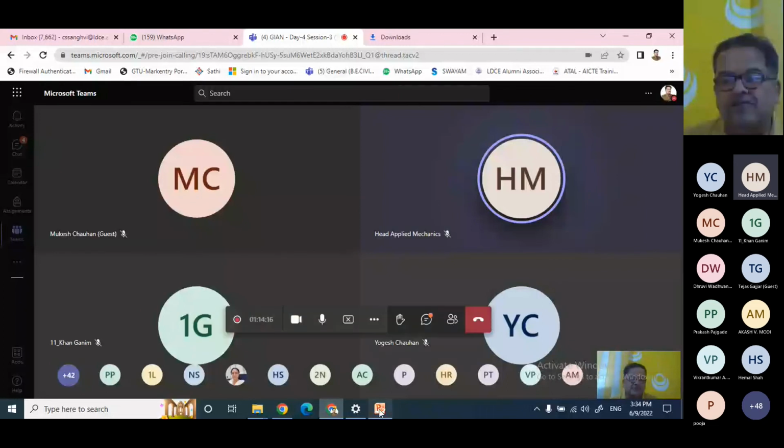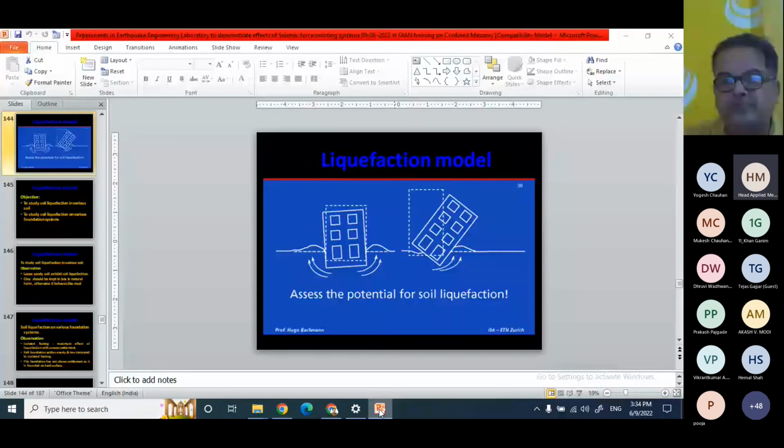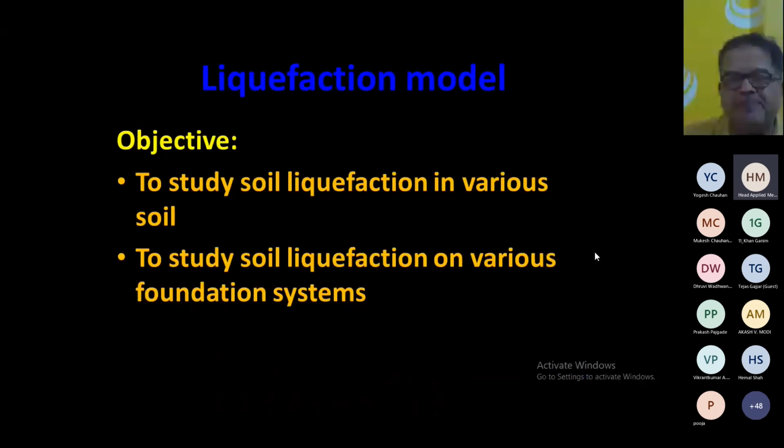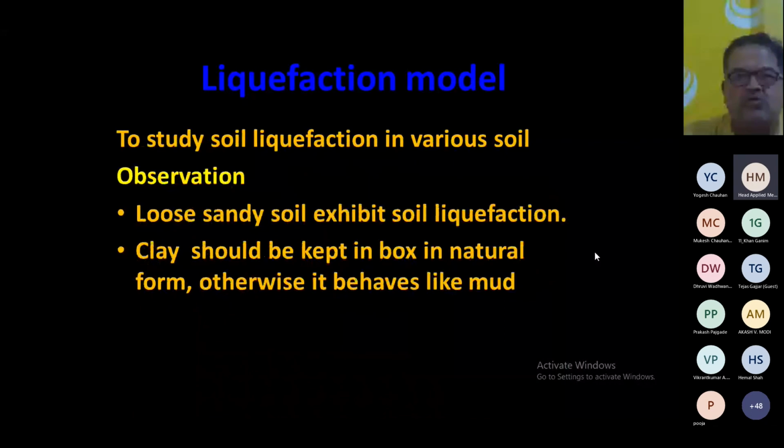We will see that. So that is liquefaction. Again, I'm saying cohesionless soil is required. Second, you need a high water table, and the third is vibration. These three things are the necessary conditions for liquefaction. So soil will lose all its shear strength because of the increased pore pressure, and then your structure may rotate like this, right? So we have created the conditions, I think.